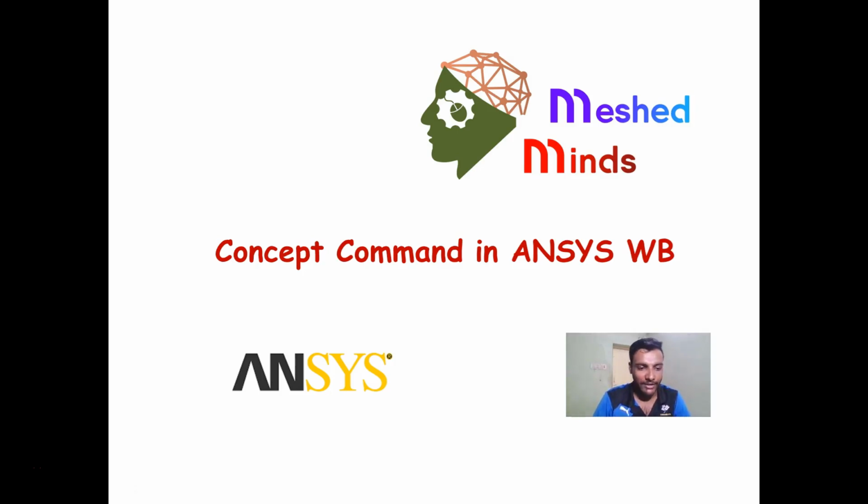Hello friends, in this video tutorial we'll be taking a look at the concept command. The concept command is a very useful command in the design modeler where we can convert a sketch into a surface, or create a 2D surface on top of a 3D surface, or create curves out of a few data points that you have already stored, or create line bodies from a series of points and so on. So let us take a look at how it works.